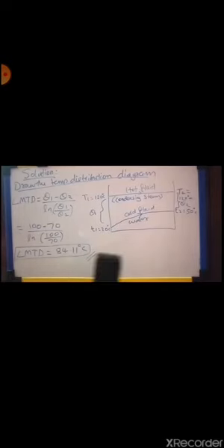The second condition given here is that the inlet temperature of water, which was actually 20 degrees centigrade, is now altered to 15 degrees centigrade. Then what will be the outlet temperature of water if the flow remains constant? If the flow remains constant, we can take the same LMTD here. It is given that the flow remains constant, therefore LMTD is the same for both the cases.